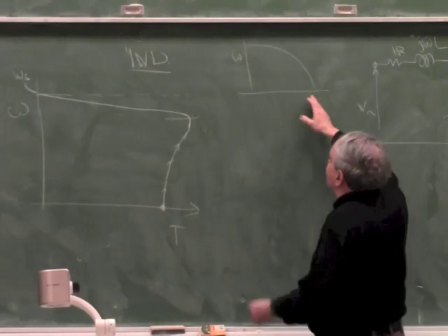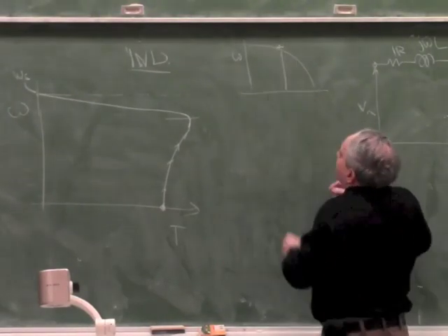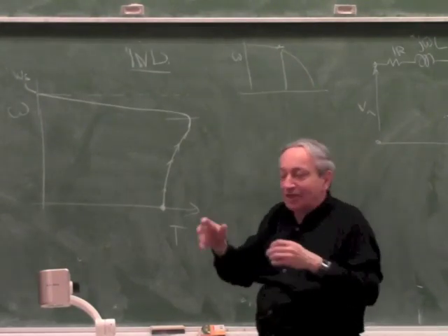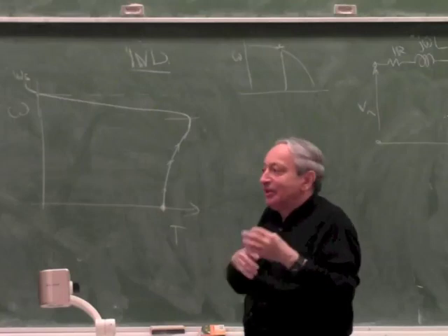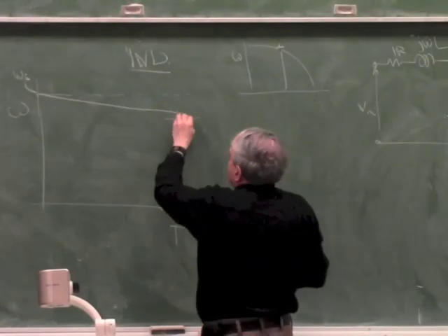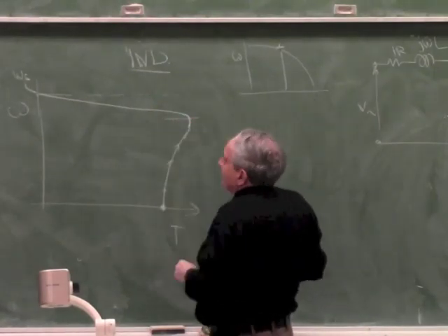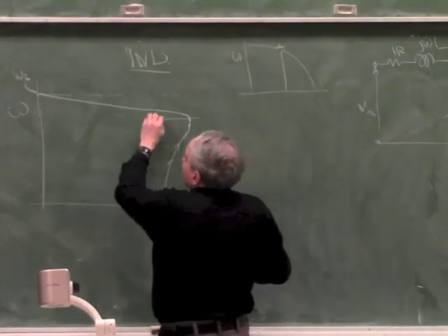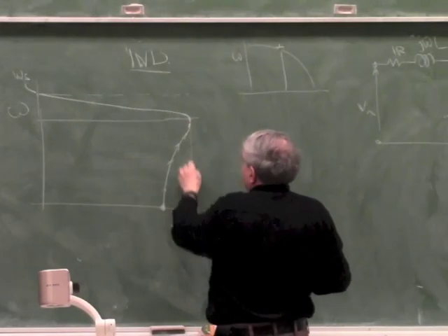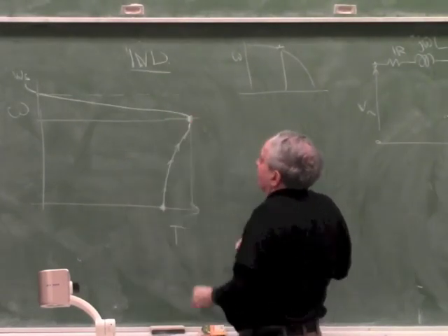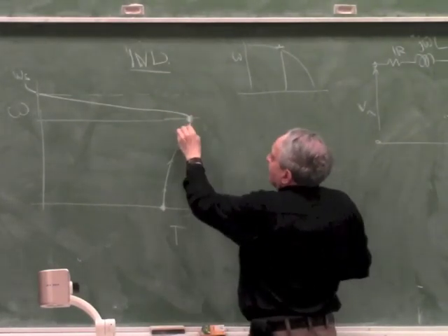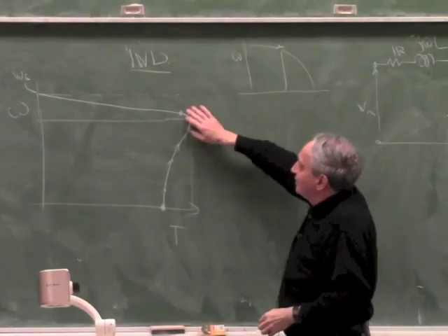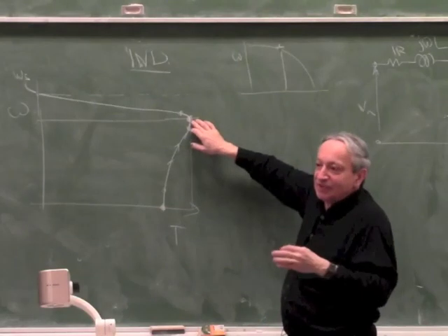But you don't like that, because you like the motor to work here, and you're trying to get the highest efficiency here. So you optimize the copper or the aluminum and the steel and the gap, and the whole thing is optimized so that it has the biggest torque, which also means the biggest power, because it's running almost at constant frequency at a working point, and you always run the motor at this point. If you load it a bit, it will go to this point. If you unload it a bit, it will go to this point. But basically, it's always working at this point of the rated torque.